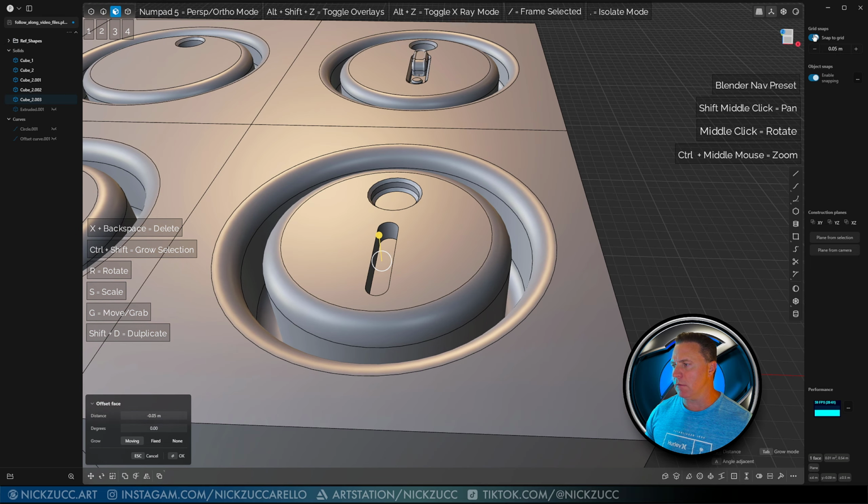So I'm going to hit undo. I'm going to tap E for extrude, and I'll extrude this in. And then this should allow us to take this ring and pull this in to do a tapering effect. Okay, now that I have that, I want to take the corners on here, and I want to round the corners. So I can do chamfers or fillets like this. And then at that point, I want to take all these edges too, and I'll hold down Alt and Shift at the same time so I can select a lot of these. I'm going to turn the grid off temporarily, and then just do something like that. Okay, so there's that shape there.